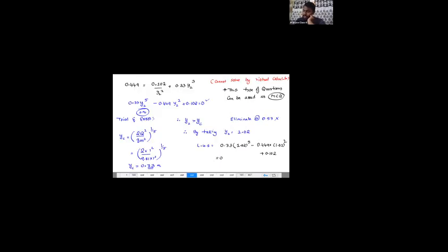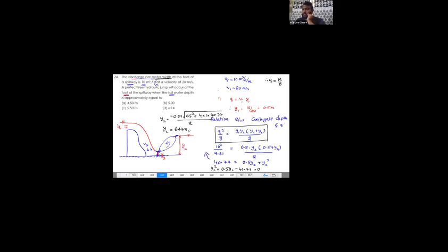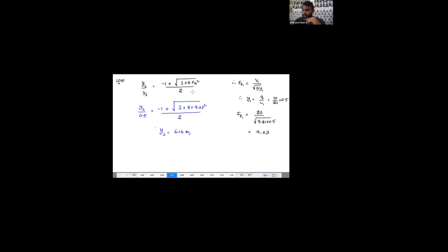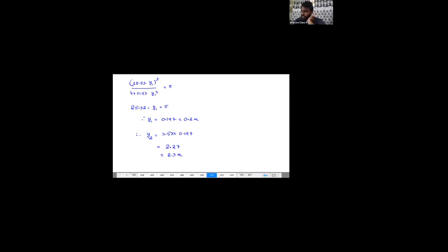That's all. So we know how to use the conjugate depths, how to determine the conjugate depths. This is for non-rectangular sections. I went with the basic approach and have done it by means of trial and error. If it is a rectangle, then I can use the relation between conjugate depths and the Q. I can use the sequent depth ratio, and also how to utilize the energy loss, and from this how to determine the conjugate depths. Okay. I hope you understood these concepts. So that's all with the